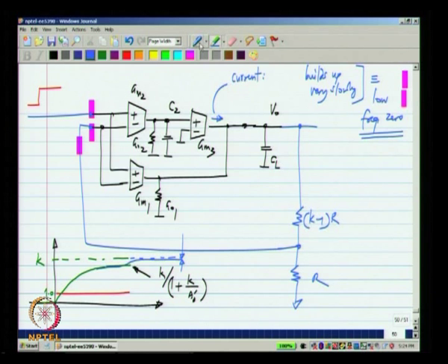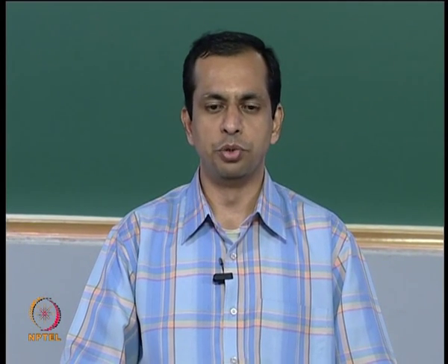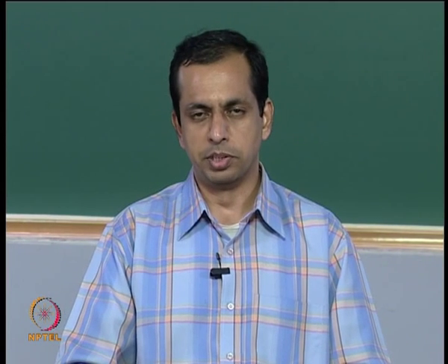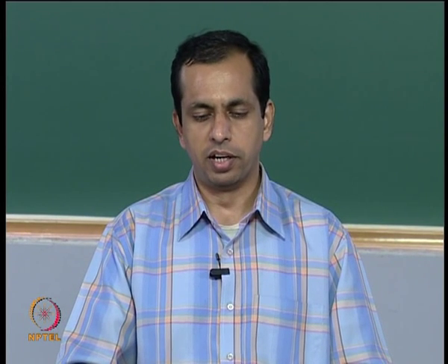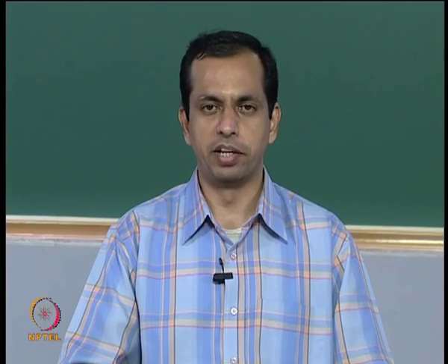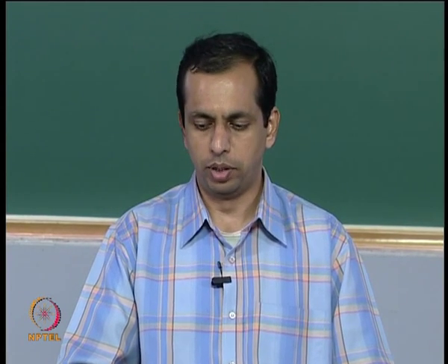Now, because of this reason, because the output builds up and then builds up slowly, this kind of feed forward compensated op amp is not necessarily suitable when you have step like inputs. When you have step like input, the input appears rapidly, this single stage responds, and these 2 stages respond much later. Okay. So, for step inputs this may not be the best choice, but for other kinds of input where you do not expect a step, the feed forward compensated op amp can give you pretty good performance. Okay.